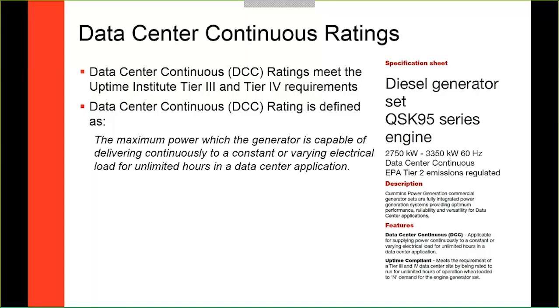In fact, generator set usage at a data center, studies have shown that typically it's at or below 30% of the generator set's rating. And so the issue here is that when you underload a generator set to that level, it can actually drive towards a solution that has increased maintenance concerns, and we typically refer to that as wet stacking on a large underloaded diesel or compression ignition generator set. And again, when we're talking with Uptime, their goal is to help facilitate data centers that are more reliable or have better uptime. And so again, you can see that there's kind of a conflict there.